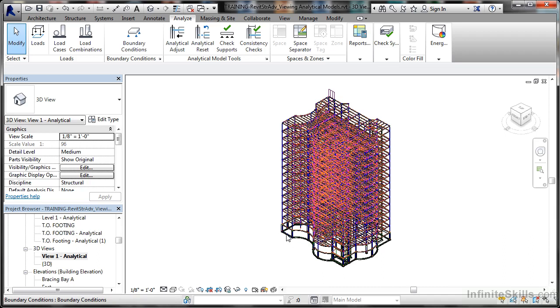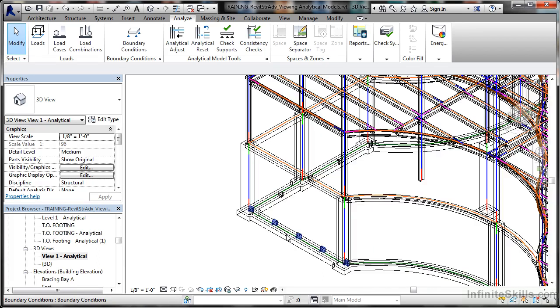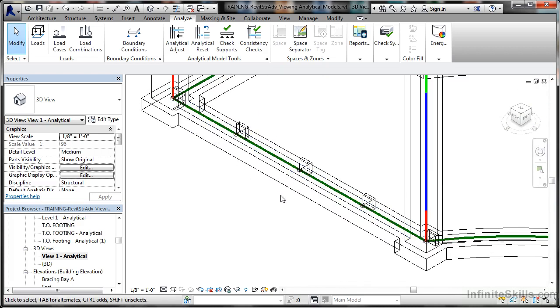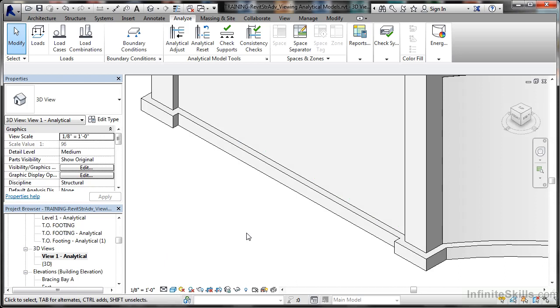And I'm down here in this corner, so let's zoom in, and there's my loads right there. You can see them there on the actual analytical wall. So what I've got to do is set the visual style to shaded here. So I set that to shaded, like so. And you can see there that I need to rotate the view now to display the bottom of the building.